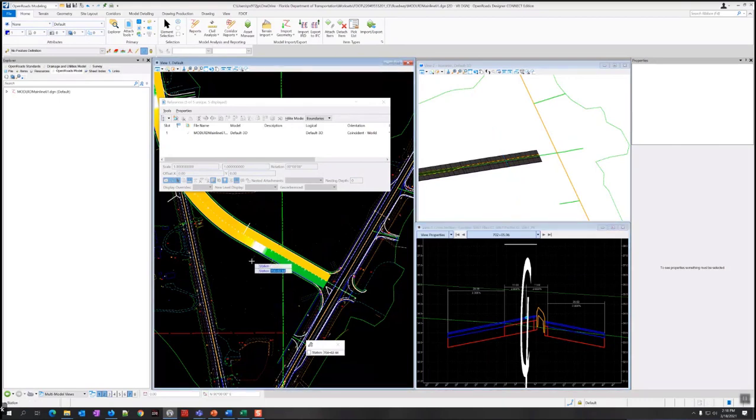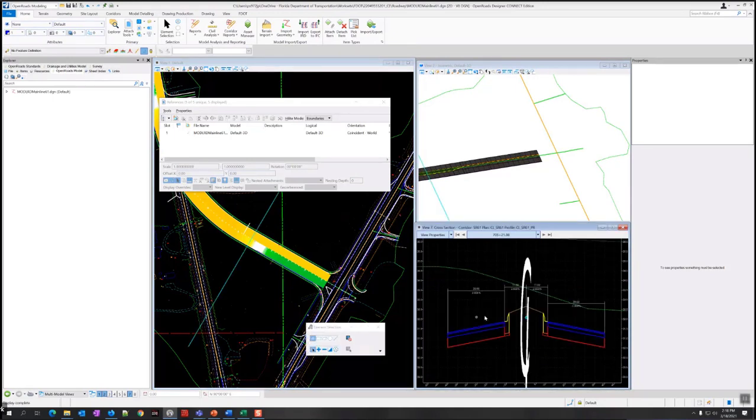Select this view, and I'm going to go somewhere near the transitions. Go over here to the super elevated section so you can see a more dramatic difference. So all these dimensions stay here. This is good. So everything's still at 2%. Nothing's applied yet, but at least we can see what it is and we can see when it changes. So that readies us for exercise 3.17.